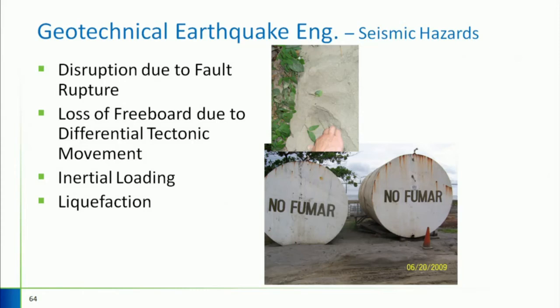When a sand in particular is vibrated, it wants to roll into a tighter configuration, so it wants to fill up the voids. If those voids are full of water, they press up against the water. If the water does not have time to escape, it builds up a pressure and pushes back on the soil.